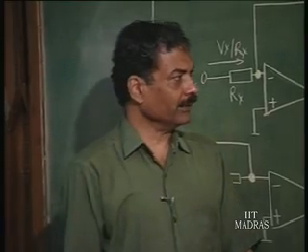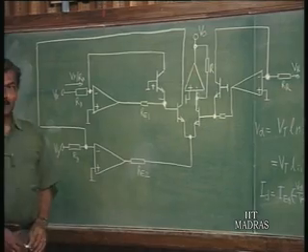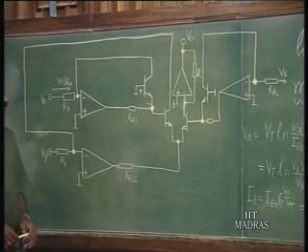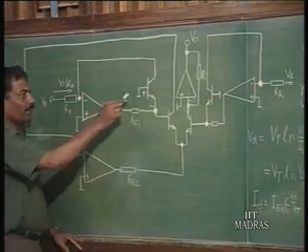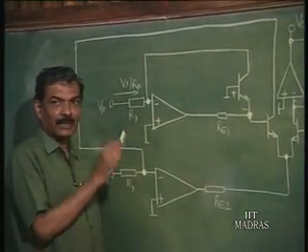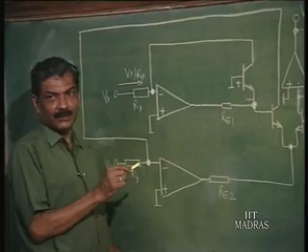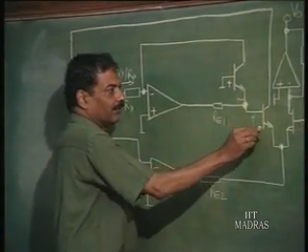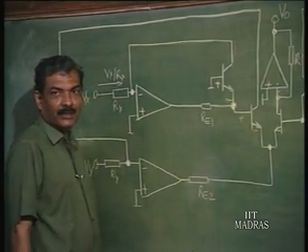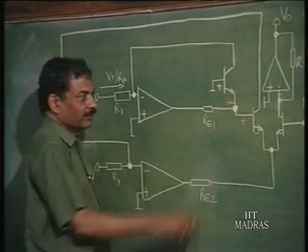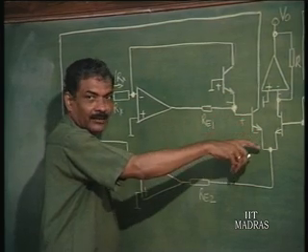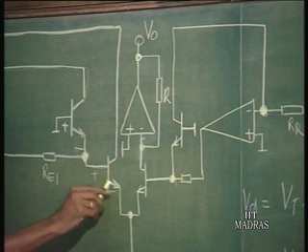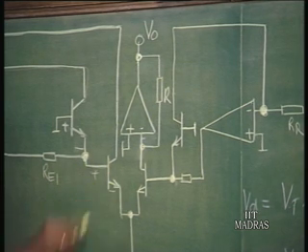Now that we have understood the presence of Re, how to select it, we can further discuss the circuit for the multiplier. So, we have already developed a voltage which corresponds to minus Vt log Vx by Rx IE naught with respect to ground. Now, to this voltage we have to add minus Vt log Vy by Ry IE naught. So, that we can add by putting another diode whose current is supposed to be equal to Vy by Ry. So, that can come in series, addition of base emitter junction.